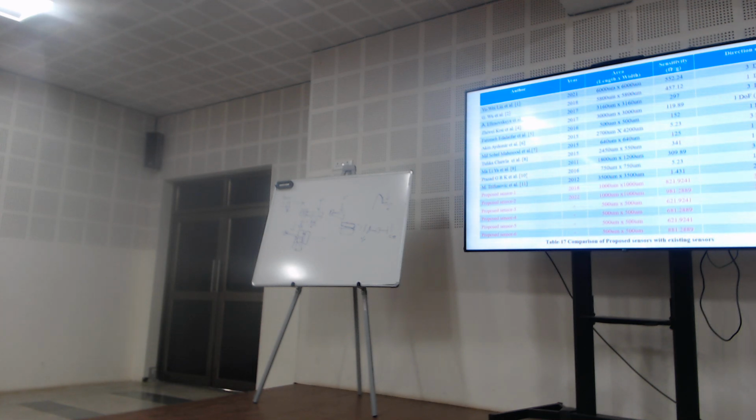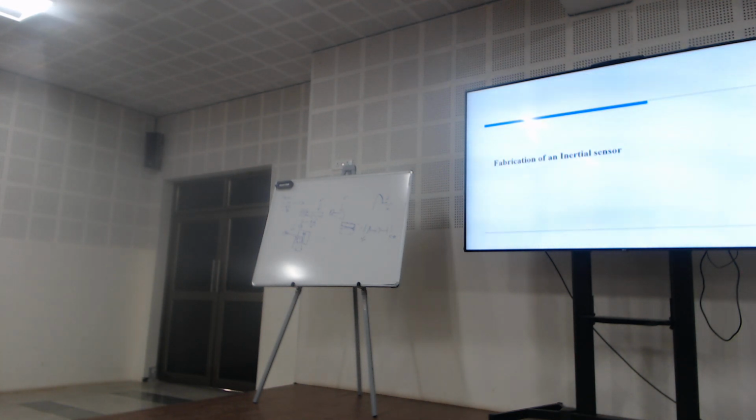So these are the different directions of sensing, and this is the capacitive sensitivity. Whenever we go for capacitive sensitivity, here we get very good results because of differential capacitance. These two are also differential capacitances, but these are not differential capacitance. That is the only matter. So these are some kinds of design issues.